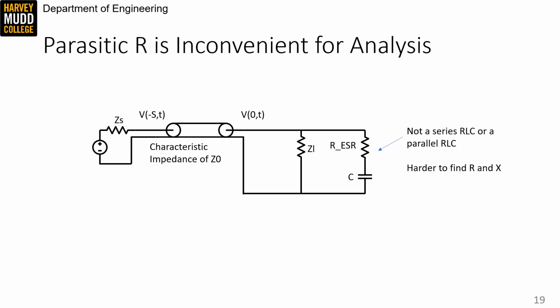However, if we could somehow swap in a model of the capacitor that had the ESR in parallel with the cap instead of in series, this becomes a simple parallel RLC circuit.